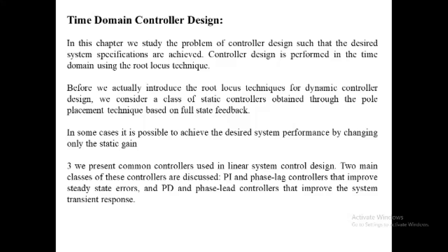However, very often a static controller is not sufficient and one is faced with the problem of designing dynamic controllers. In this section, we present the common controllers used in linear system control design. Two main classes of these controllers are discussed: PI and phase lag controllers, which improve the steady state error, and PD (proportional derivative) and phase lead controllers, which improve the system transient response.